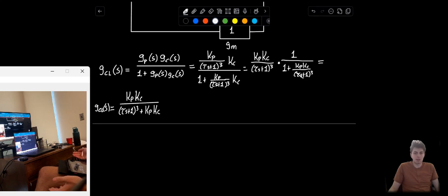We're going to make the assumptions that tau and kp are values that we cannot change. However, we do know that the denominator of this equation is the characteristic equation of our control scheme. And what that means is that wherever the roots are real, we have a stable system. So, we could attempt to try and find the roots that would make the system work.